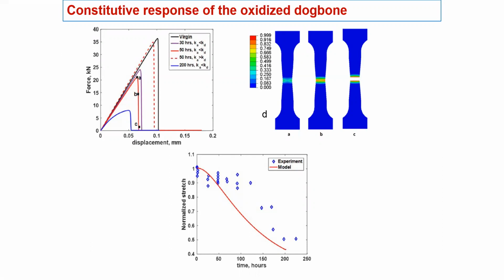Another interesting thing is that with this, we simply minimize the energy, and damage propagates where Griffith's critical energy is reached. So we don't need any different criteria for crack initiation, propagation, crack branching, or kinking. We just let our model find, based on the energy, where damage should start and propagate. So it's very handy when you want to use this phase field fracture method for constitutive modeling of fracture.